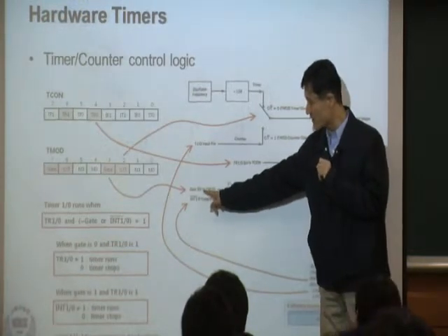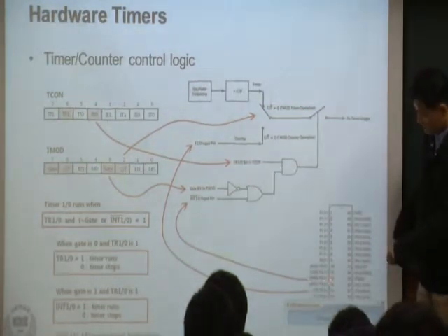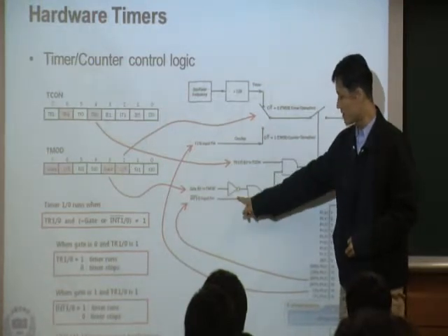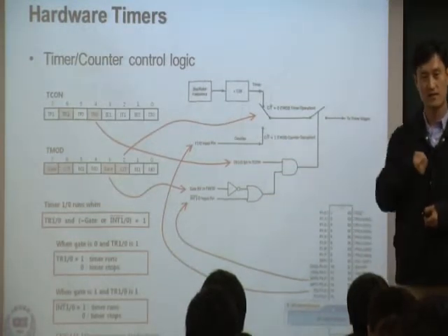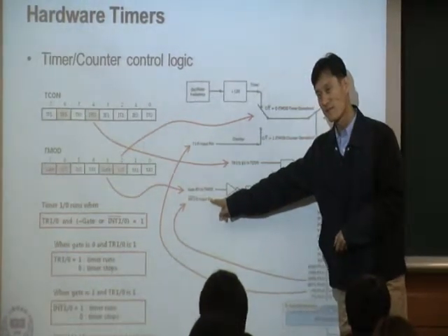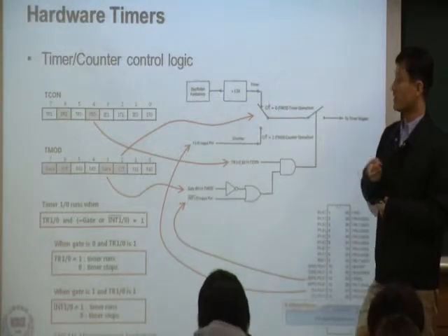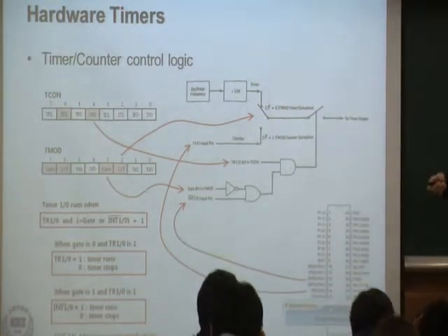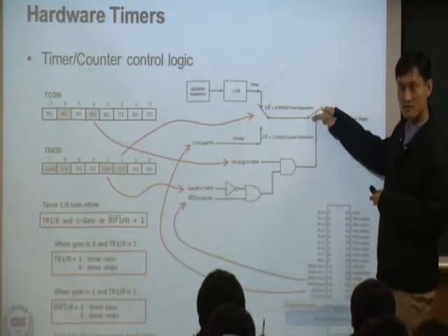Okay, you are enabling gate by setting this 1, and this particular second one is interrupt 1 0. What is that? That's this pin. Based on this pin, now you are gating. If I make this 1, then it's 1. If I have a 0, then it's 0. Okay? So now I'm gating. Sometimes if I want to enable it or disable it, disable it by this pin. Okay? Based on this pin, I want to enable it, disable it. That's called gating. So in order to do gating, I want to have this bit, gate bit to 1. So that's hardware logic. So all these things is to eventually make this 1 or 0. That's what we want. Okay?